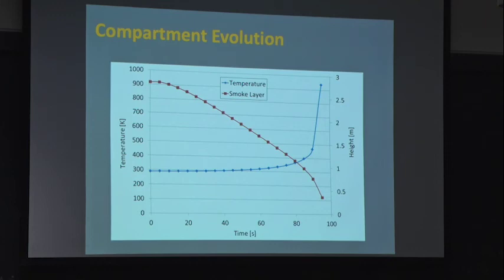Yep. Do we need to consider the flame height interacting with some of the upper layer? Yeah, of course. I think what ends up happening is that the solution becomes incorrect much earlier than that. So clearly, at some point around here, the flame is going to start interacting with the smoke layer, and the flame opens up, because you get the hot gases pushing the flame down, and the flame cannot push itself through the smoke layer, so you get a flame that opens up, which effectively reduces entrainment even further. So somewhere around here, all this thing is going to break down. Okay? And all these things have to be considered.